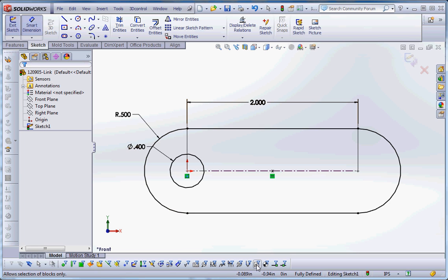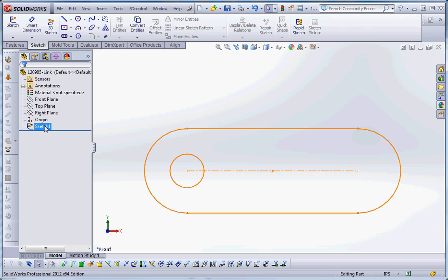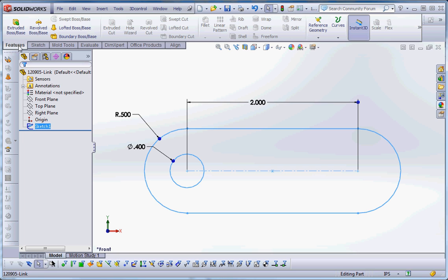Remember that the slot tool automatically takes into consideration some of the elements that we would like to have in there. For instance, the tangential relationship between this curve here and that line, and that line and the curve over here, and so on and so forth. It's all set up for us and ready to go. So let's go ahead and rebuild that. Let's go to our sketch, because we're going to borrow this. We're going to do that in two different features.